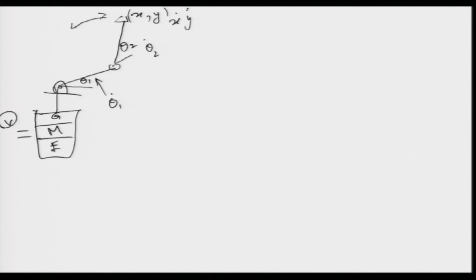So, what we need to do from the controller point of view is to find a relation between the motor, the joint velocities and the end effector velocities, and this mapping is very important because is it a 1:1 mapping, is it a many:1 mapping? Are there cases where we can give a joint velocity and the end effector does not go anywhere? For example, if I have my arm like this, at this point the position and orientation of my arm is fixed. So, if I give a series of joint velocities, you can see that the joints are moving, but the end effector is not moving.